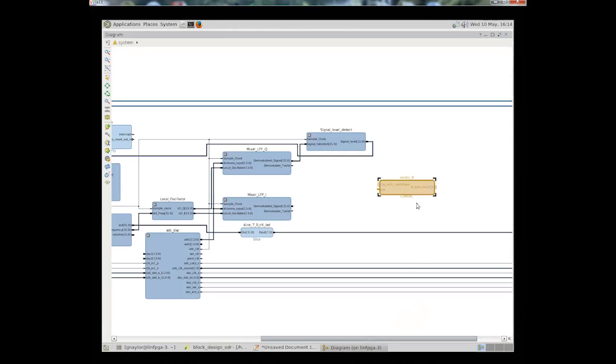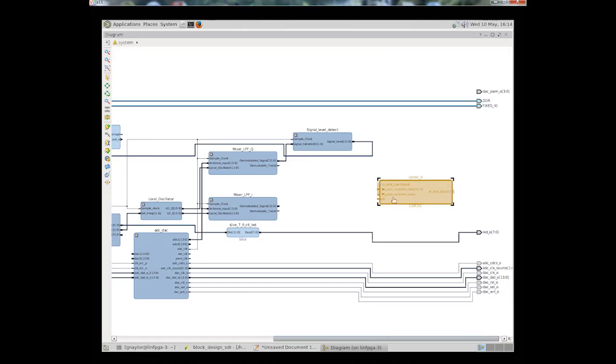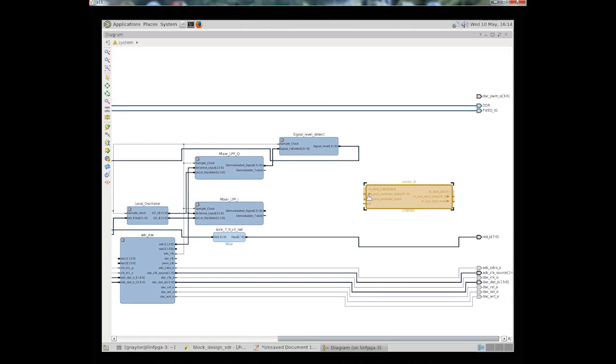So that's okay. The next thing to understand is how the data comes into this device. So it has 32-bit inputs and 32-bit outputs. The input actually has the I and Q amplitudes concatenated together as 16-bit values, and similarly the output concatenates the amplitude and phase, and in fact the amplitude is in the lower 16 bits.